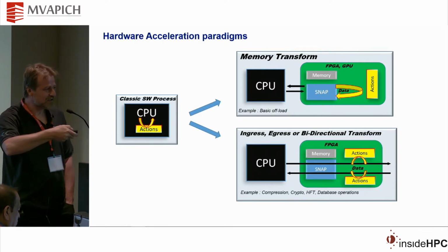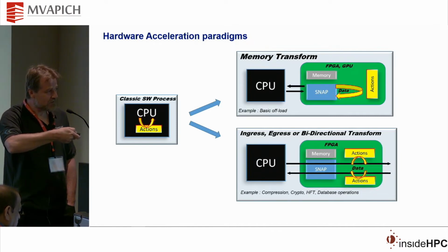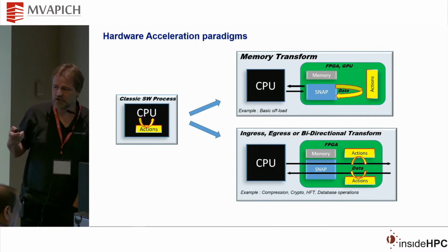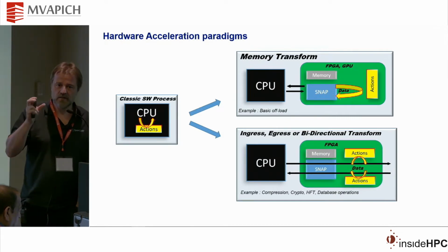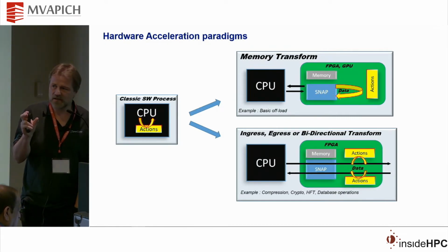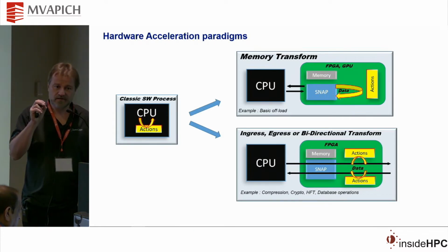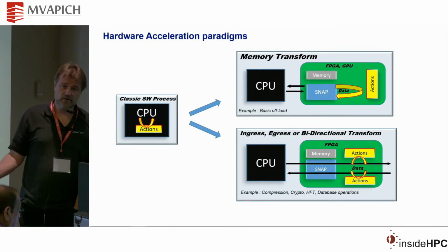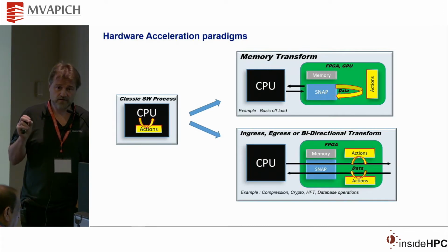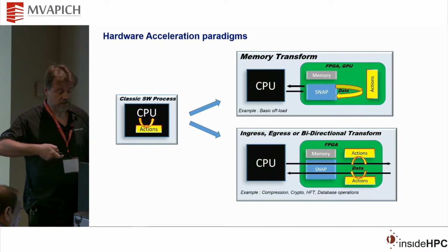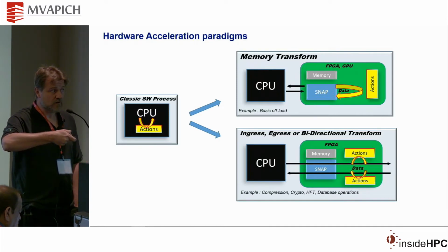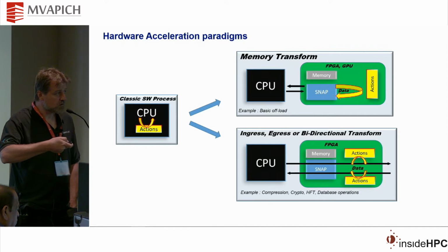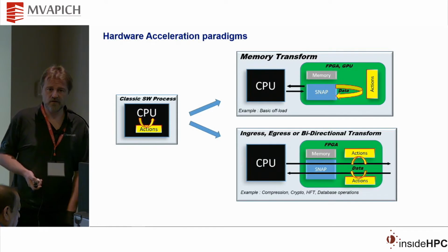It's a funny thing, so you can exactly, in the FPGA, have the NIC function be performed, and you could manually, almost mechanically, electronically check with registers that you have programmed yourself, the header and the type of header. If the header comes from this department, you say no, this is not correct, and you raise an alarm. You can raise an alarm locally that is handled manually, for example, or you can come back to the system if you want. But you can handle everything here outside of the operating system.